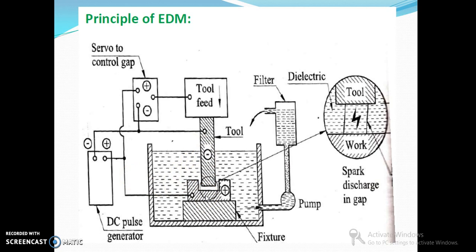This movement of electrons is visually seen as a spark, and electrical energy is dissipated as thermal energy of the spark. With the very short duration of a spark, the temperature of the electrodes rises locally to more than their normal boiling point, and this heat of the spark melts a tiny bit of metal from the work.